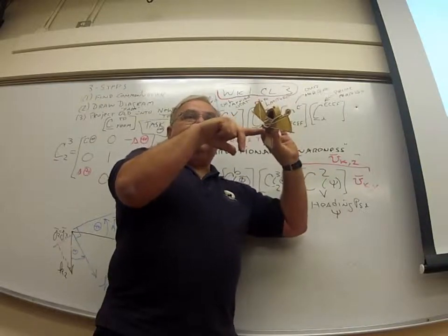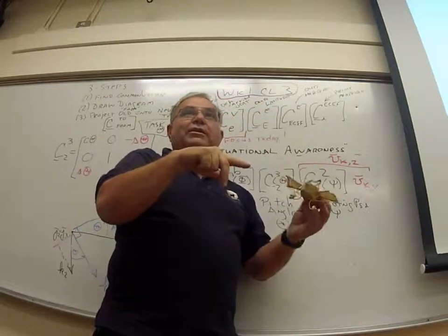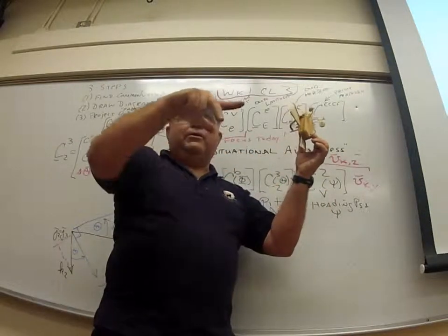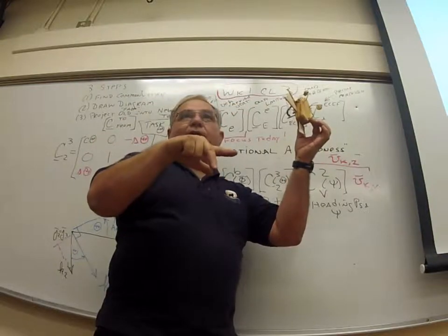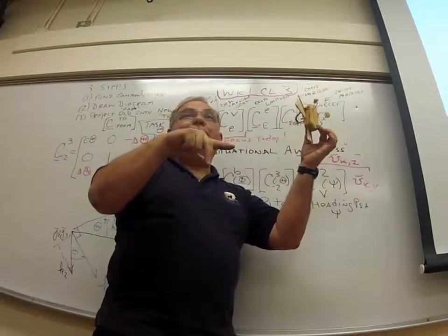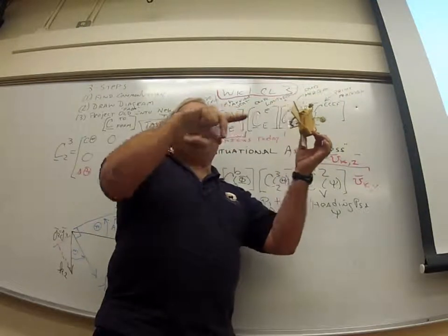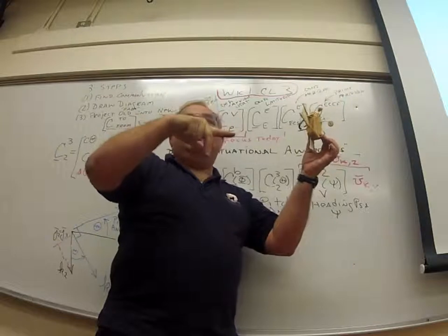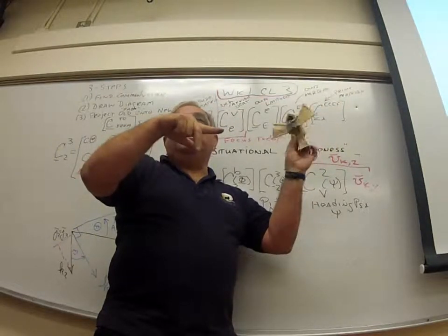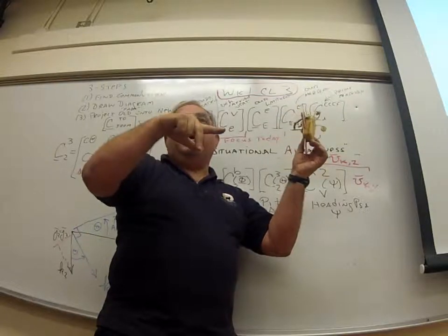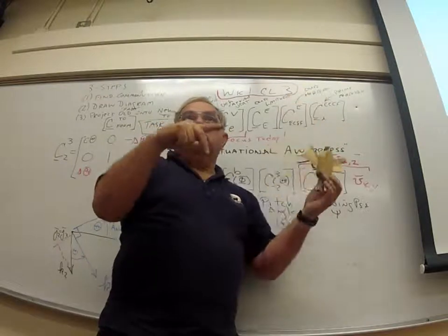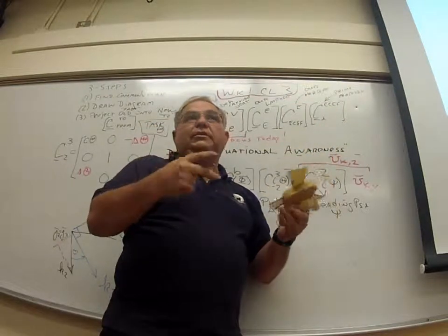There's one catch. What if I start from here? Here's my northeast down. I'm starting here. Where am I going to roll my wings to get into a... I'm already in. My wings are already in the plane parallel to the horizontal plane. So no matter how I roll, my wings are already in a plane horizontal. I am screwed. So when you go straight up or straight down, the order procedure we chose breaks down.